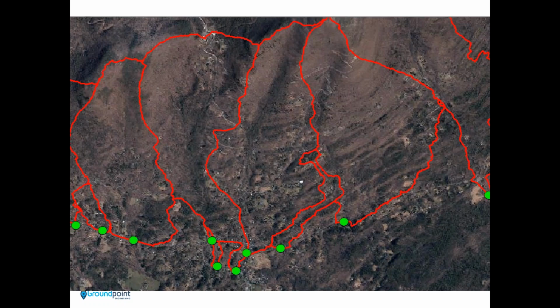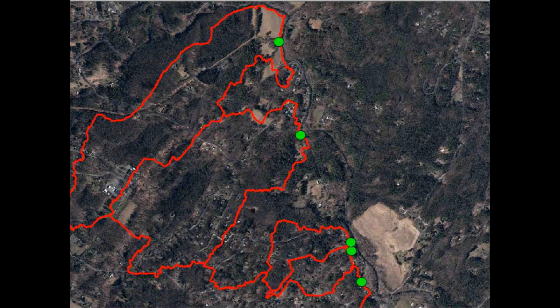And that's where having local knowledge or even additional notes in the culvert inventory data set when they're collecting it in the field can help us resolve problems like this with the GPS data. So this is how it looks graphically laid on imagery. So we throw points on there and we generate our drainage areas, and then we can QC them based on our knowledge of the ground and looking at imagery and LiDAR together.